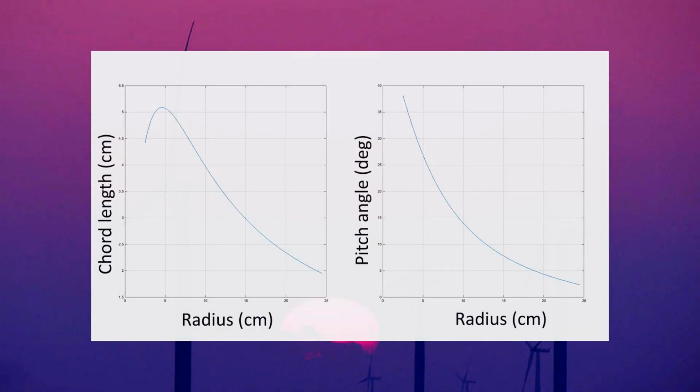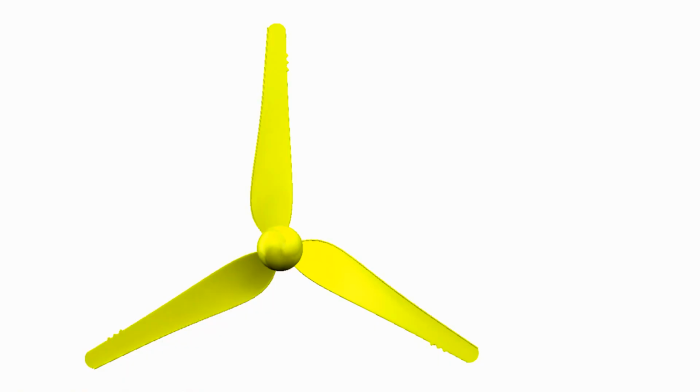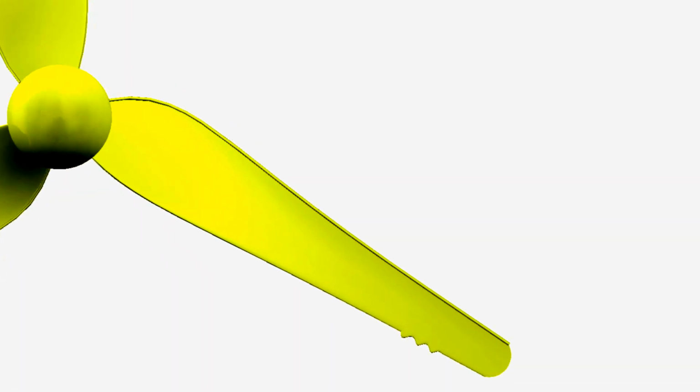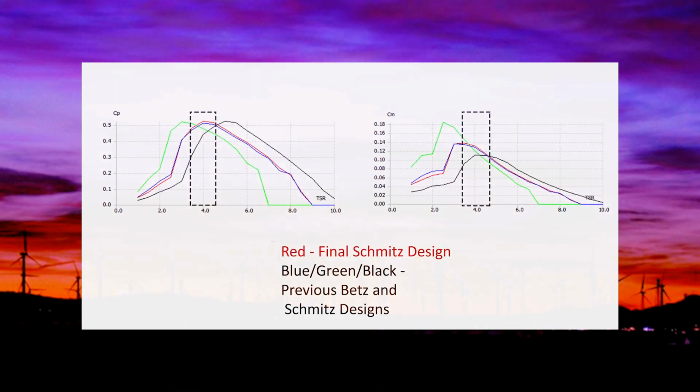Next, MATLAB was used to calculate the optimum chord lengths and the blade twist with the Schmitz model. The lift ranges from a minimum of 1.3 newtons at the root to 27.5 newtons at the tip. Drag was minimum at the root chord at 0.02 newtons, while maximum drag occurred at the tip at 0.4 newtons. Our wing tip was also chosen to be rounded, as this reduces tip vortices and also makes it easy to manufacture. We then recalibrated our Q-blade design based on this data, and the performance of the new blade exceeded that of the initial blade design.